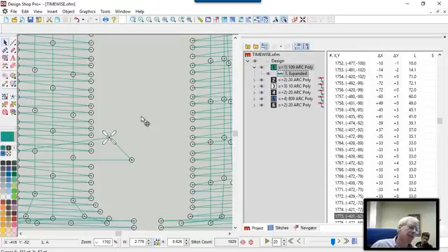So it's a very slow process, but sometimes you have a bad corner, something like that. A few extra stitches added or removed can make a big difference on a thread break every time it gets to that color. So, like with your wireframe editing, pay attention to what your cursor is doing. If you are over where the thread is and the cursor has a little line beside it, that means you're over that stitch and you can add a point. If you're over a point itself, it'll look a little bit different. So just pay attention to what the cursor is doing so that you know what you're really grabbing a hold of, and that really helps.